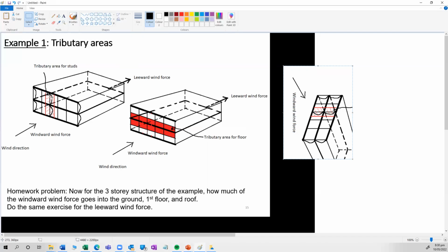So just remember, that's how it works. Just think of it as a floor. You just rotate it 90 degrees. It's just like a floor, isn't it? And these are like floor slabs supported by these. Imagine these diaphragms, the floor and the roof, to be long beams over which slabs are supported.